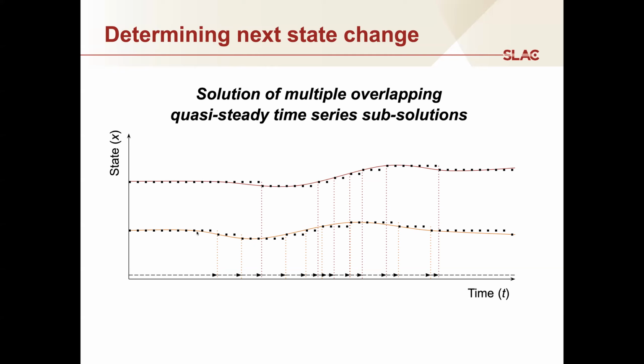You answer the forward question, what is the state given the time step? And then at that time step, how long before you see the next state change? And then it knows how long to advance the clock by, and ultimately the simulator advances the clock by the maximum time it can, given what it knows about upcoming state changes in objects in the model. So that's the basic idea.